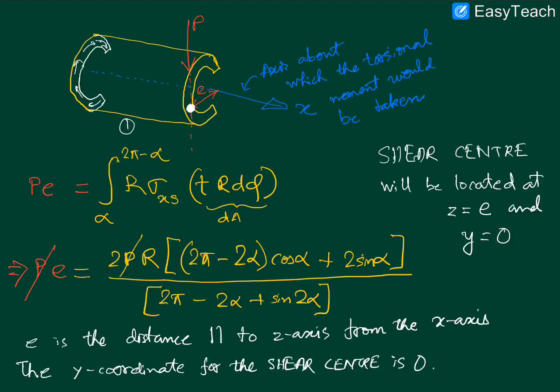It is important that we maintain our cross section to be thin walled as well as open ended, which is why you can make alpha as small as you want, but you cannot take it to be equal to 0. A little slit has to still be open at the value of phi equal to alpha being very small.